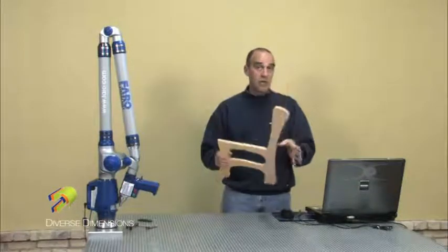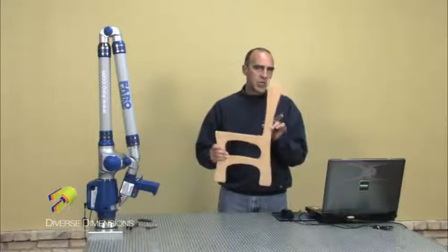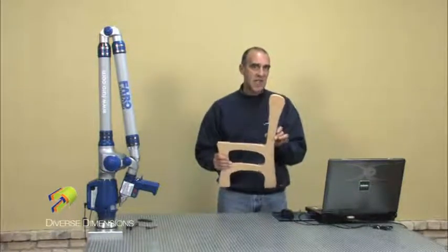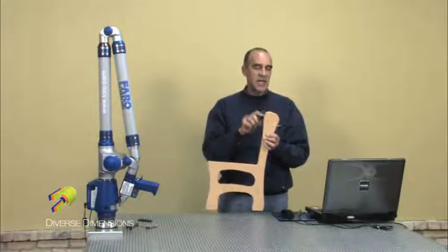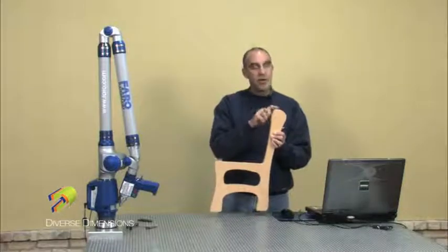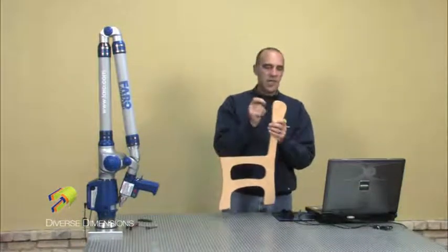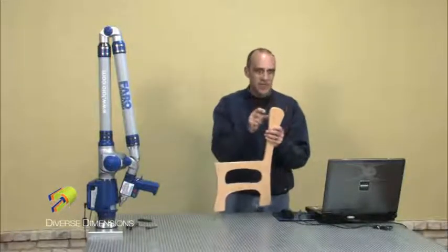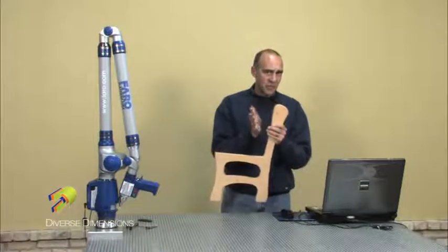But one thing I do want to make a note of is for sure remember this too. When you do splines as a 2D freehand scan, you don't have the ability to extract points from the data set. Say if I was coming around this curve here and I came off and then I came back down, you don't have the ability to pluck those extra points out that were solved as you were coming away from that chair part. So polylines works great for that.